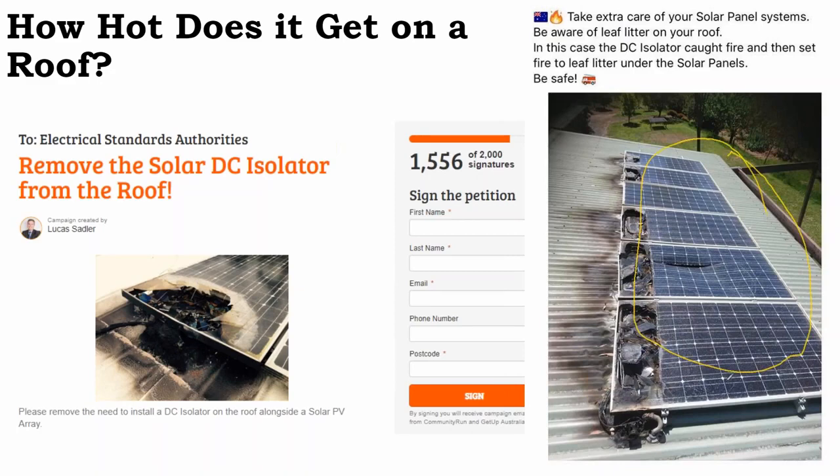And so the problem becomes, when you build a solar array, you're like, oh, I need to have a box up on the rooftop. So you go to Home Depot and you buy a box and a terminal bar, and you're not using solar specialty parts, but you're just using stuff that they have at the supply house. And this more generalized balance of system material might only have a 60-degree temperature rating or a 75 C temperature rating, whereas everything else, your solar cable, your solar panels, the inverter, everything else in the system is designed with a 90 C temperature rating.